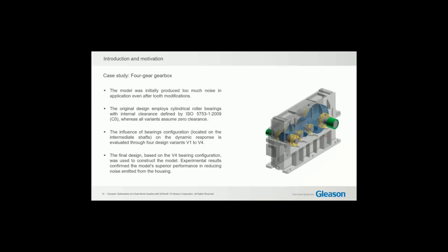So what was the problem that we focus on in this case study? The model initially produced too much noise, even after applying some tooth modifications. Based on the collaboration with the customer, they tried another optimization level. The original design employs cylindrical roller bearings with internal clearance. The bearings are defined as ISO 5753, and all variants assume 0 clearance.